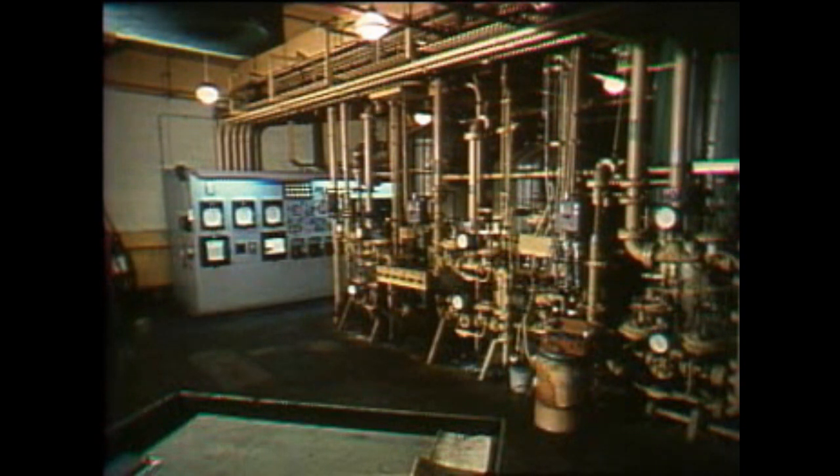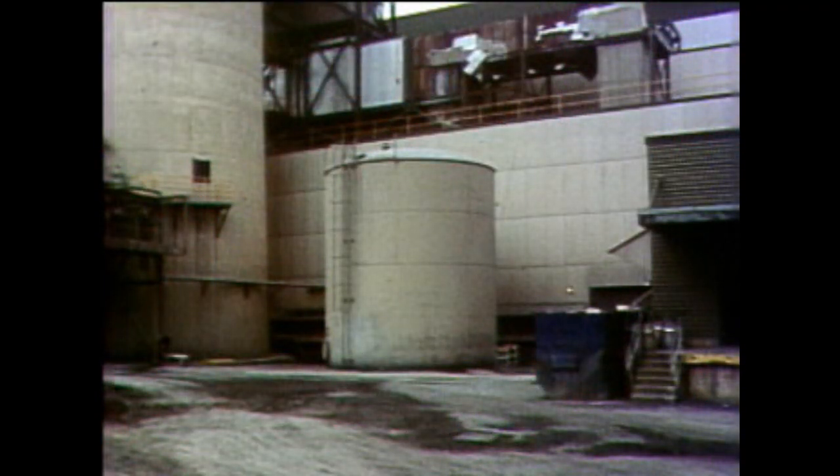Water that's used in the steam cycle must be purified to keep scale and foreign material from accumulating in the boiler. The make-up water system purifies the water, which is then stored in tanks until it's needed. In this topic, we looked at three important components involved in the power plant steam cycle: the boiler, the turbine, and the condenser. We also discussed some systems that support the steam cycle: the boiler fuel and air systems, the condensate feed water system, the condenser circulating water system, and the make-up water system. Take some time now to answer some practice questions about what was covered in this topic.